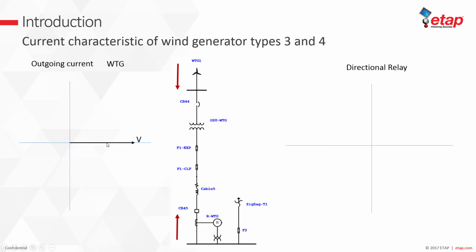So we take the voltage as a reference, and the current would be the y-axis. In this case, the right hand side, the first and fourth quadrants, represent the active power greater than the auxiliary power, and the left hand side represents the power generation by the WTG, wind turbine generator, less than the auxiliary power of the WTG.